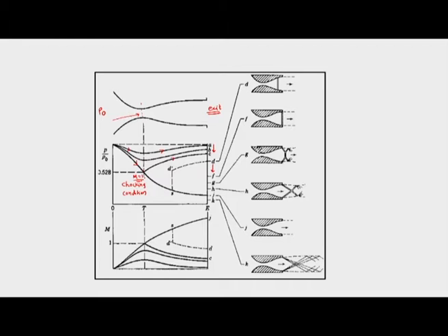So, once the choking condition is reached, then what would happen? Then we will encounter a shock here onwards into the outlet section. The shock flow is expanding into the diverging section, but we do not have sufficient outlet pressure. If the flow continues to expand into the outlet section, then it will have a pressure which is much lesser than the outlet pressure. So, the flow would have over expanded.